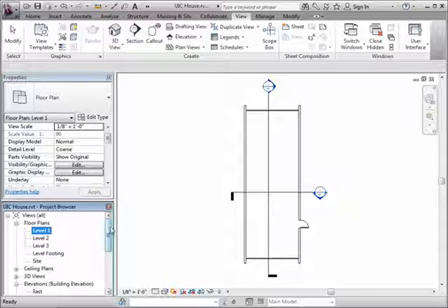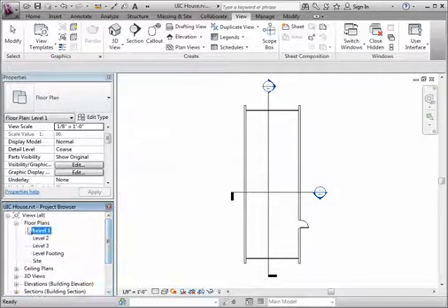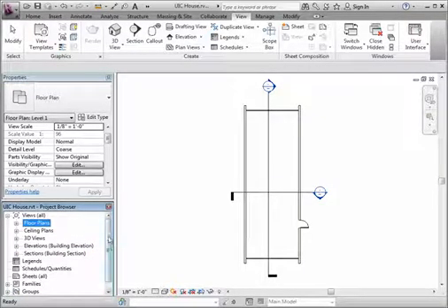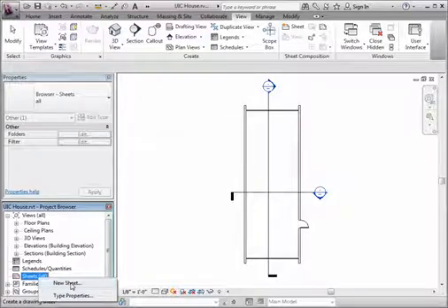Okay. So let's make a sheet real quick. I mentioned to you at the beginning that there's one file and that everything exists in one file. So these are all the views. Down here, this is where all the sheets exist. So unlike a project that I've worked on before, you might have 50 or 100 or 200 sheets listed underneath this part right here. So for us right now, there's nothing here. You can see there's no plus sign. So I'll right-click on the word Sheets and create a new sheet.